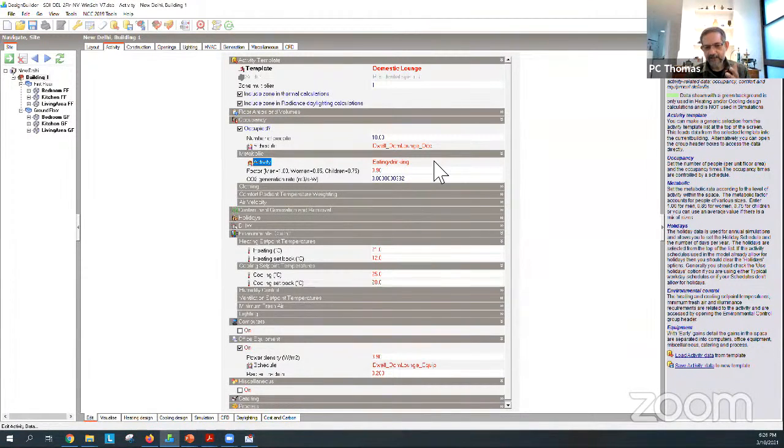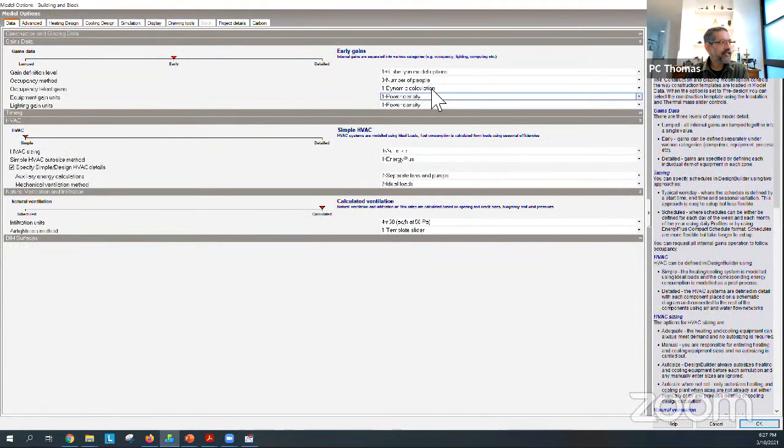Okay, typically it's around 60-40, but again, you will find some numbers in ISHRAE, in ECBC, in NBC, somewhere you'll find those numbers. But what you do is that you go to the same model options that we did the settings for. And if you want to fix the amount of latent load, then you can change the occupancy latent gains from dynamic to fixed.